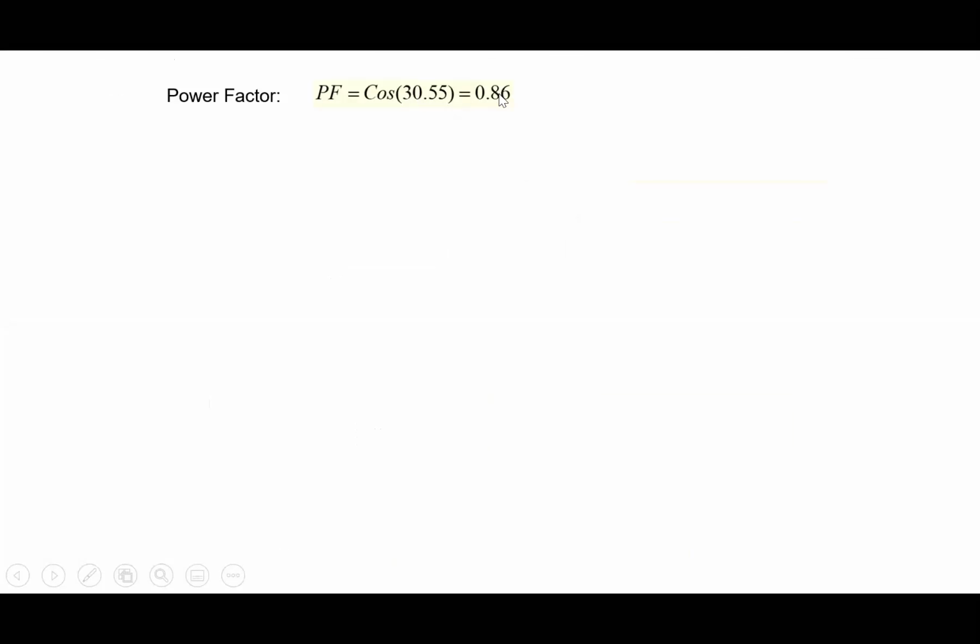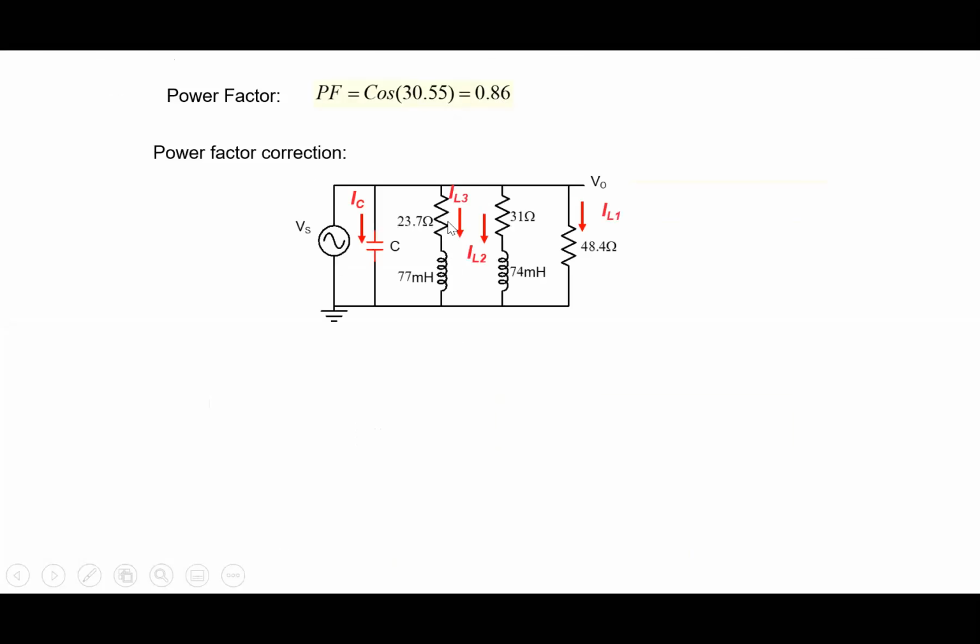So ideally, I would like power factor to be 1, so this angle to be 0. And therefore, because these all have inductive components here, if we add a capacitor here, this capacitor would draw some current, but its phase would be opposite to that, and a cancellation can occur such that I can have 0 angle between current and voltage here. So that's what we are requiring. And so in this case, now we have IC, all these things that are there here. And this is the current that is drawn in the capacitor here, 311 omega C angle 90 here.